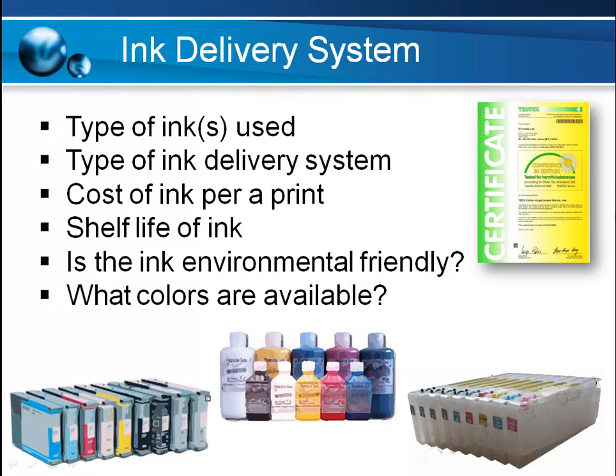The reason why I focus on cost per print, different inks have different viscosities, and the lower viscosity inks require more ink consumption. So comparing a lower viscosity ink's cost per liter might not be equivalent to a cost per print when you're using a higher viscosity ink that requires less ink to be used.